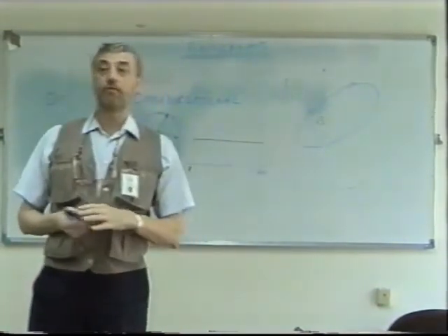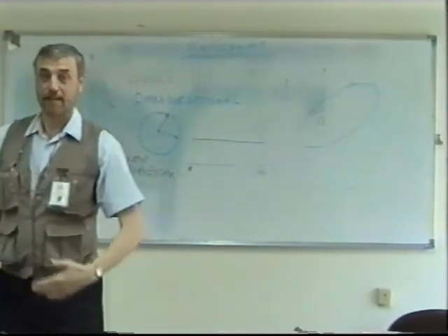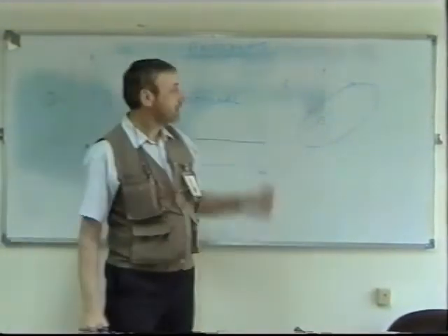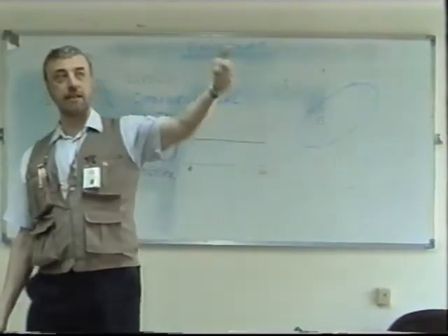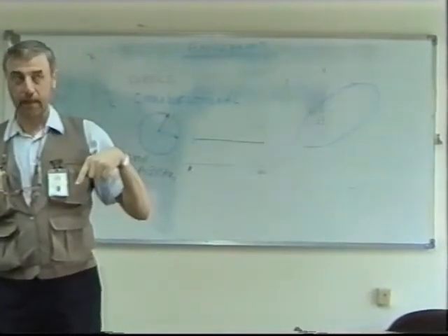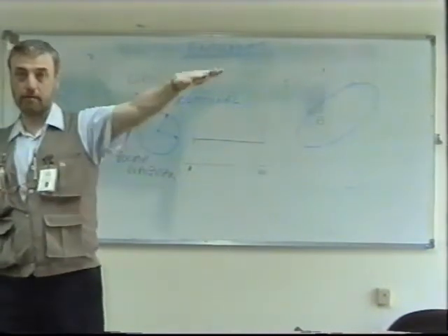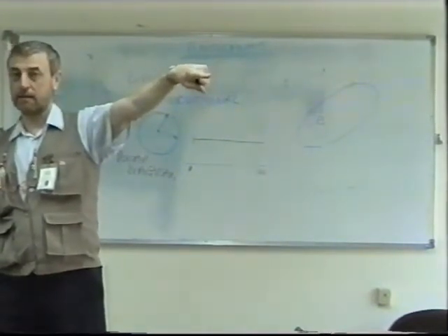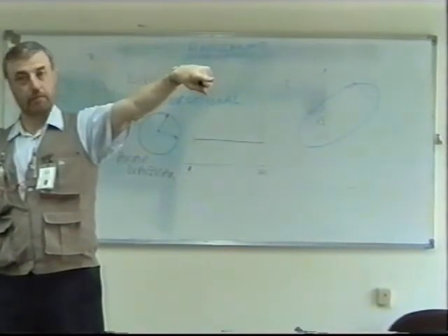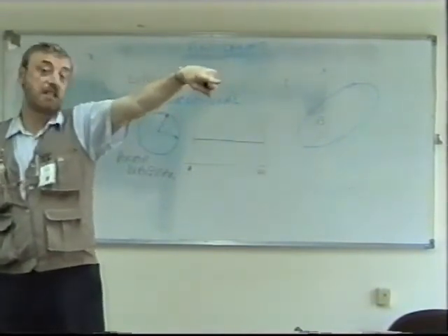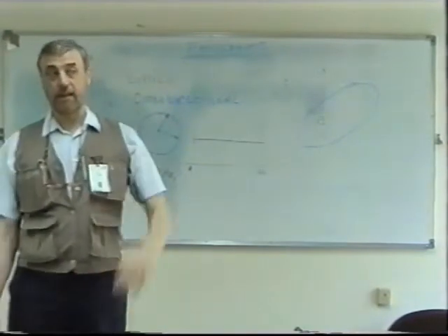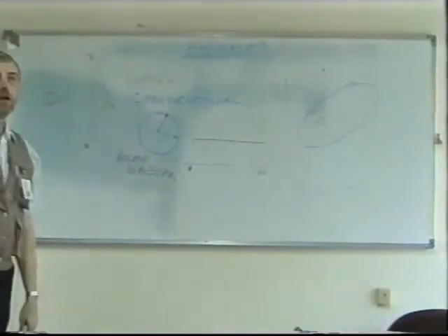But when somebody talks about the range, you know, when somebody talks about the range, we're saying, can you receive my signal or can you not? And a quick answer is, well, are you within visible sight? If you're not, probably you won't be able to receive the signal. Distance is not the issue. The fact that it does get weaker, yes, just make your receiver more sensitive. More gain in the receiver and you'll make up for that.